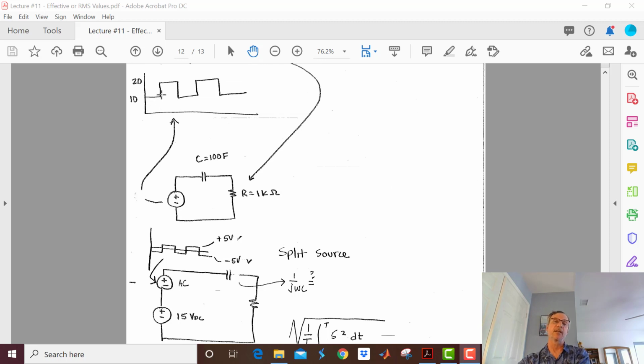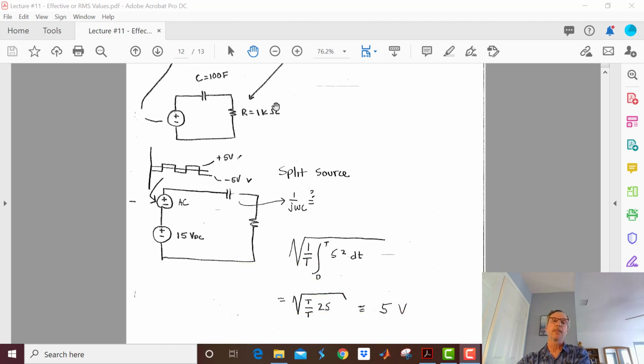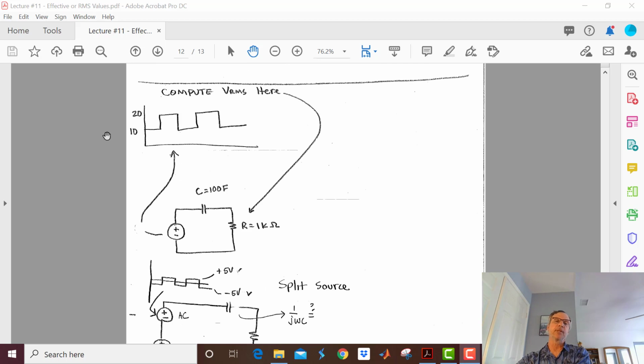It's going to go from 10 to 20. So if I'm looking at the oscilloscope, if I'm in DC coupling, my waveform will be up here. If I switch over to AC coupling, it'll fall down and be symmetrical around 0.